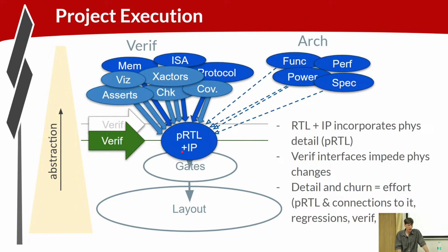You might be messing around with the encoding of signals to optimize the implementation of your state machine. Maybe you need to take a state machine where the states are encoded values, right? If you have 8 different states in your state machine, maybe you originally designed that with states that are encoded as 3-bit values. Timing's not working. You can optimize that by doing one-hot encoded states. So you encode them in 8 bits instead of 3, and only one will assert at a time. That's something that tends to reduce logic depth.